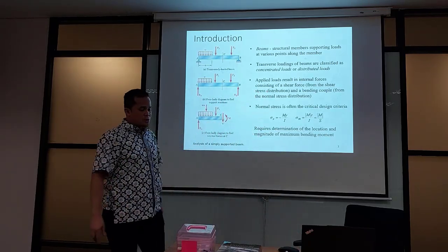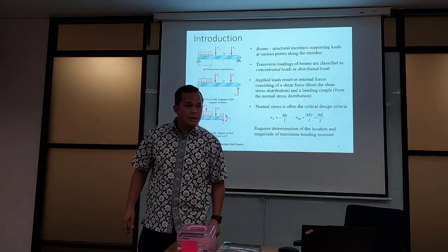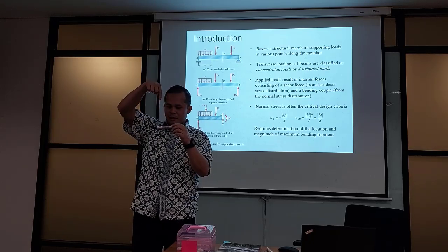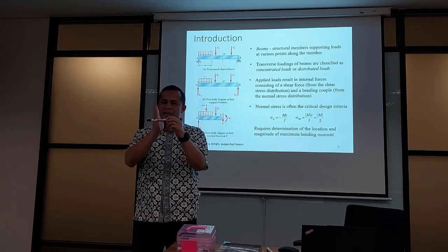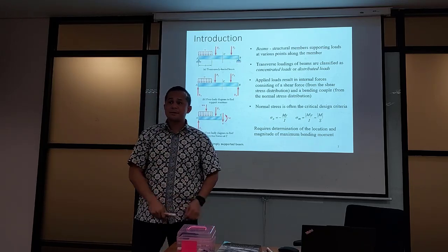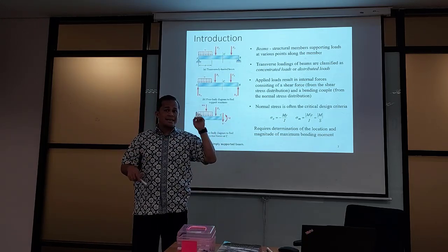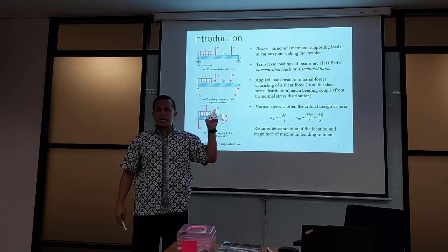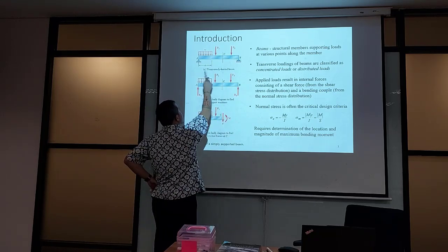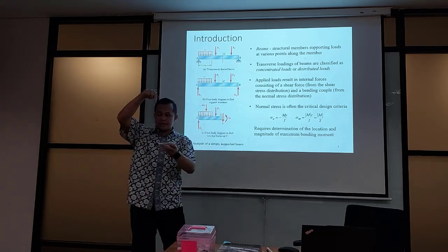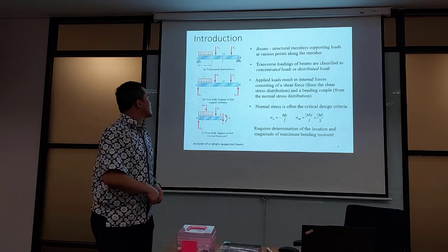First, I would like to introduce what we call a transverse force. What is a transverse force? You are applying a force in a transverse direction, perpendicular to the axis, or parallel with the cross section. In the previous chapter, I demonstrated how bending load is generated by tensile load, but this time, I demonstrate how bending stress can be generated by transverse load. All of these are transverse loads because they are directed perpendicular to the axis. Okay?